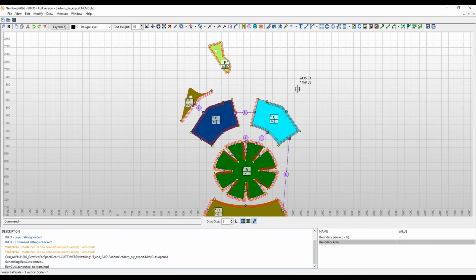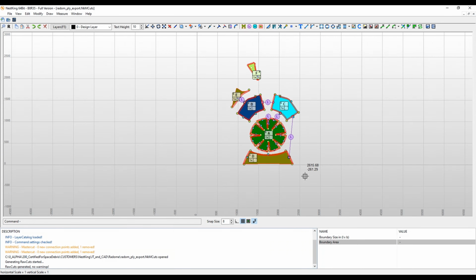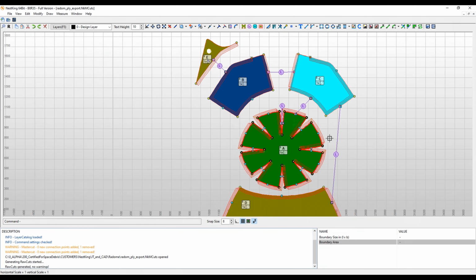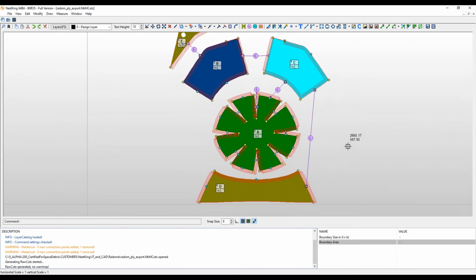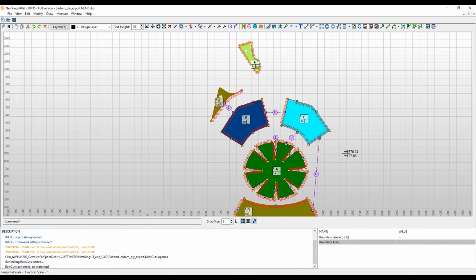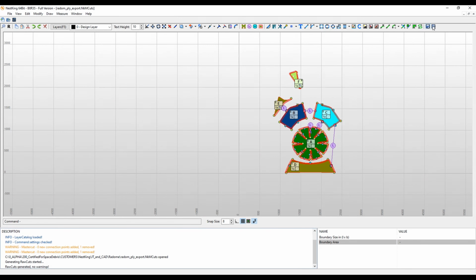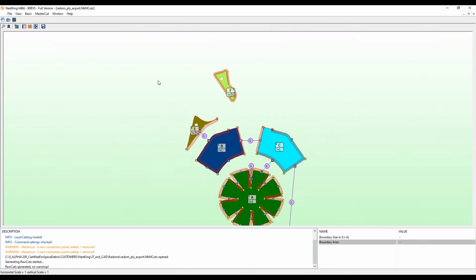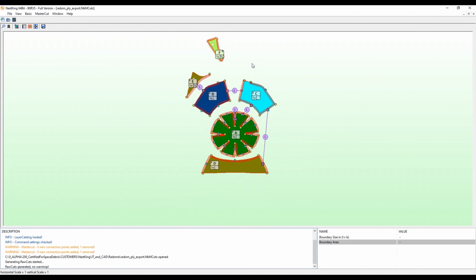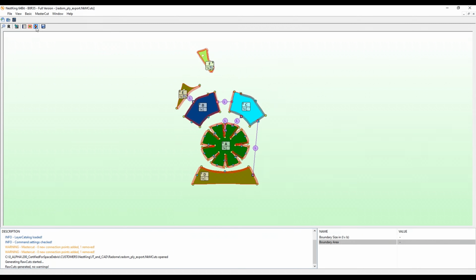So now this is everything you need to do to create your ply stack for this component. One final look if we forgot anything. No, all looks solid to me. So we can save and leave the sketcher. And the next and last final step is to create the nested output. And therefore we are going to generate master cut output.